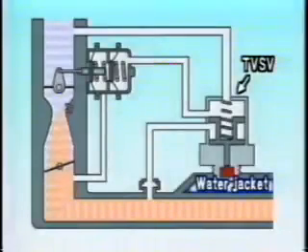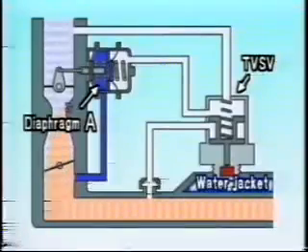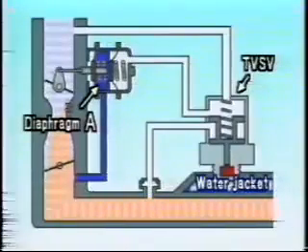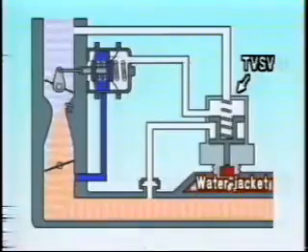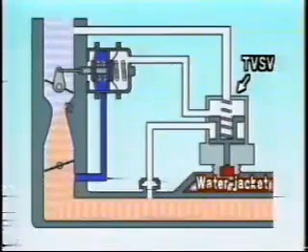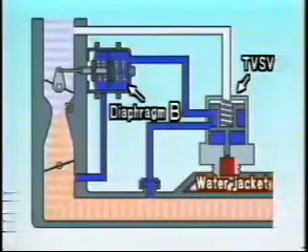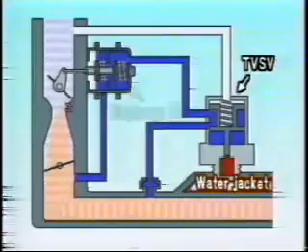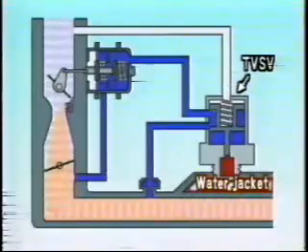When the engine is started, the low intake manifold pressure causes diaphragm A to slightly open the choke valve. Till the engine warms up and the coolant temperature rises to normal operating temperature, the TVSV opens, and the vacuum from the intake manifold causes the choke opener diaphragm B to open. After this, the choke valve is operated by the auto choke mechanism.